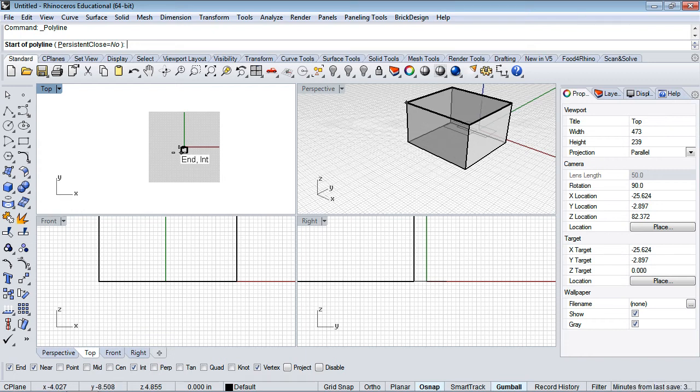It's snapping at the first geometry, not at where on the construction plane I might want it to be. So what you can do is have it ignore that and go to the construction plane. So now it snaps down to the bottom so that it's on your construction plane. So that can be helpful, making sure things are all on one plane, so you don't have any kind of wonky stuff. This gets more important when you get into surface generation.